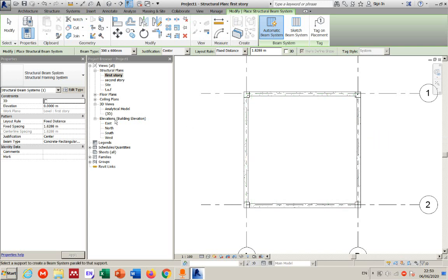Now the beams here, the beam type can be seen from here. If I don't have something within the family, you cannot select it here. Look, for example, I don't have smaller than this one. So if you want, you can escape, add them, or you can edit them later. Because normally the joists in the beam system we use will be smaller than the perimeter girders. So the small ones will be joists, normally smaller than the girders.